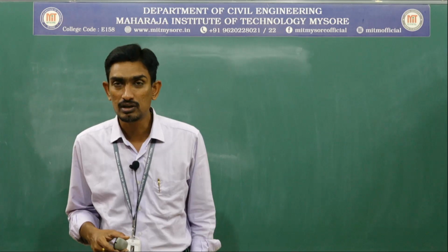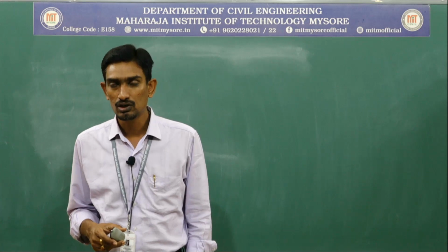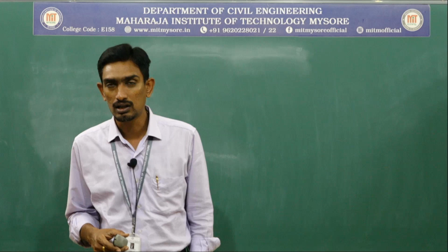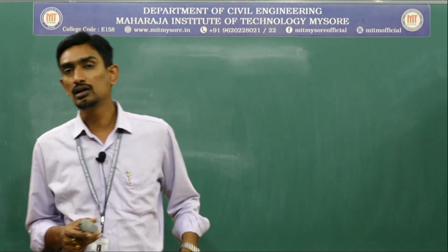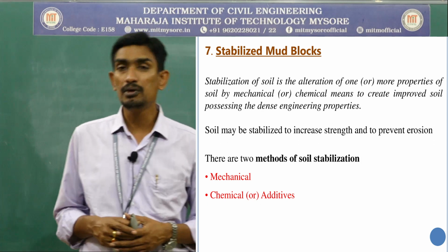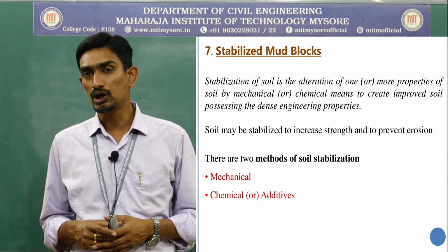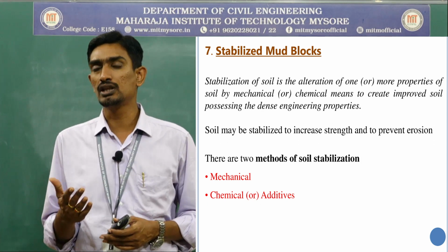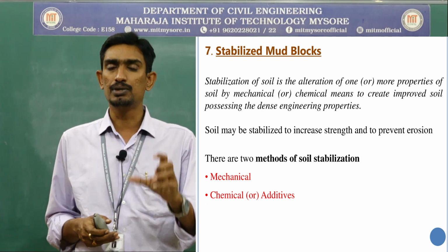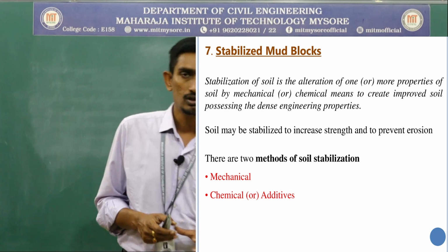Hence, the clay bricks demand heating. That means one, you need to use fully soil, and another one is the heating process. Another drawback of this clay brick is, if you want to produce more compressive strength, just like a concrete block, we cannot produce it because it is a completely soil material.